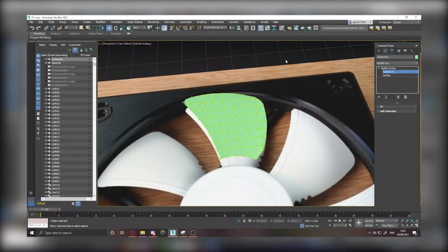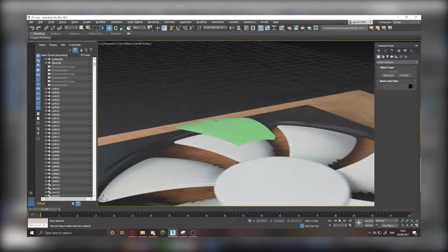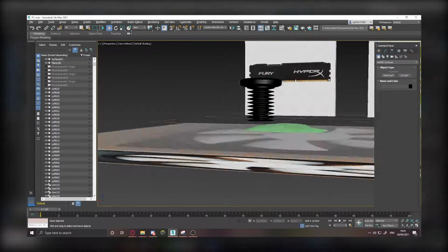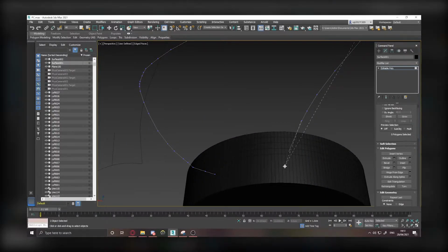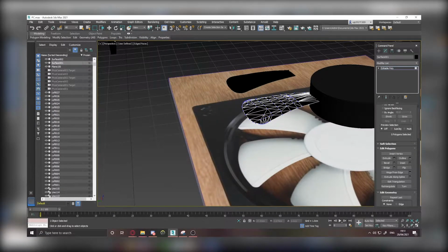I also had to keep readjusting the vertexes, as sometimes they'd be positioned too close together, causing the lighting to bug and making the blades look unsmoothed. Originally, my solution was to try and convert the NURBS surface into an editable poly after I'd made my shape, and create a new face on the underside of the blade. However, this wouldn't work due to the complexity of the curve.